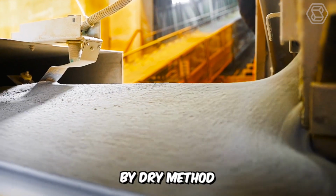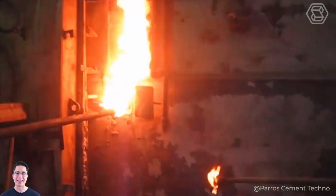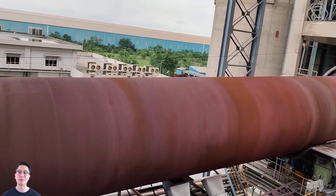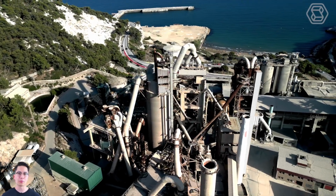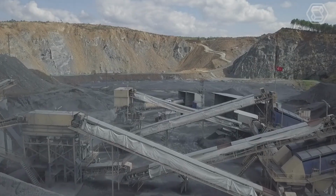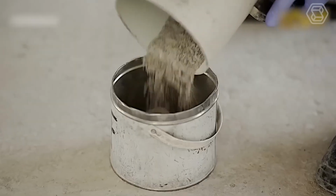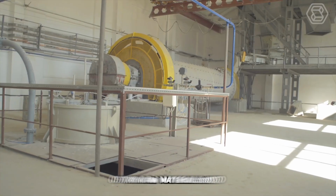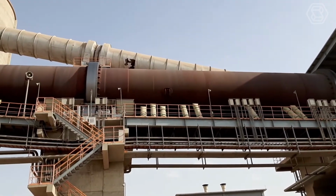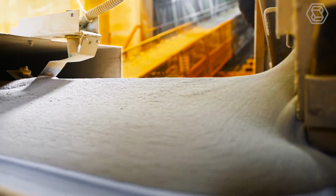Technology of cement production by dry method. I'll say right away that from the perspective of economic profitability, this method is the most attractive. Apparently, that's why it's also used in almost every large production facility. What are its peculiarities? Firstly, it's the dryness of the components at absolutely all working stages. The basis of material production is based on the chemical and physical characteristics of the raw materials used. Each of the elements is necessarily subjected to an additional drying process and then ground to powder.